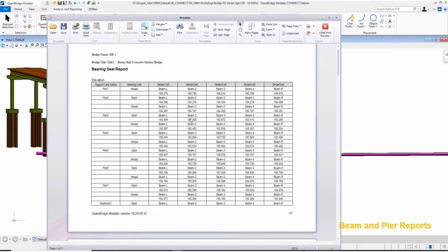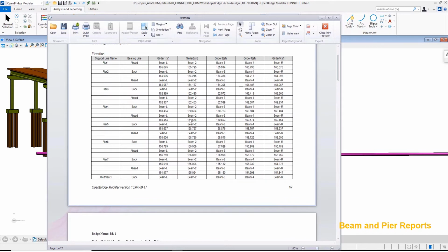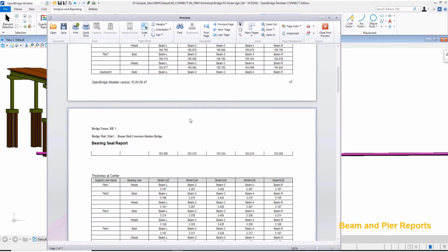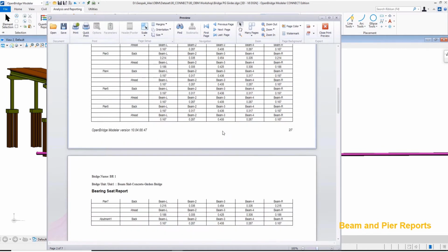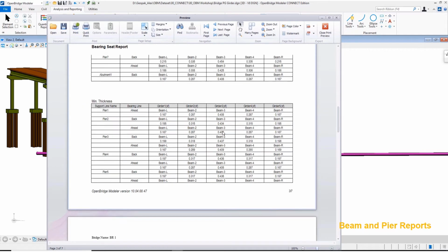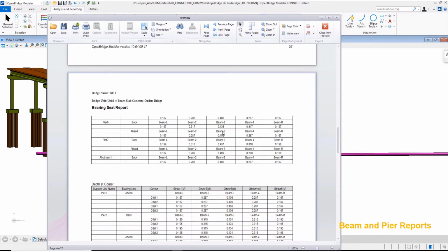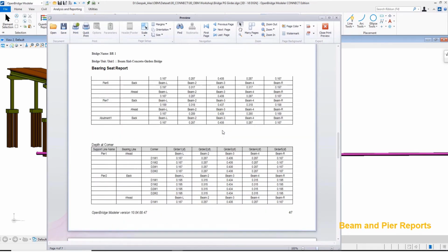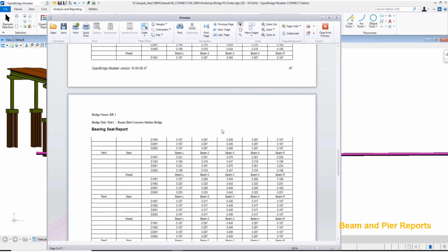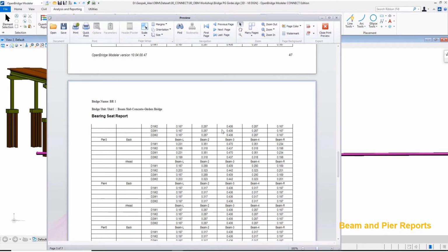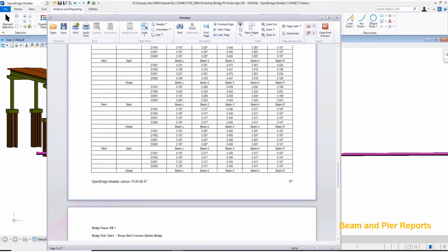If it's in super or not. So we can also give you the elevations and locations of the four corners of that beam seat and see, well, if it's appropriate or not, or whether you can accept the geometrical calculation or not, depending on the geometry you are getting, for example, for a heavy super elevated section. So maybe not use beam seats, but maybe step the cap of the pier, right?